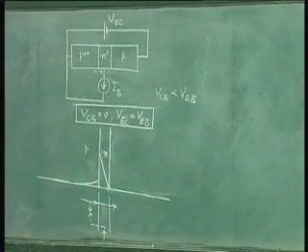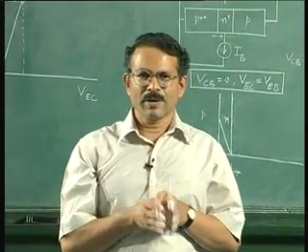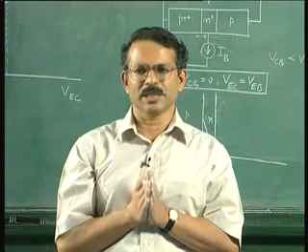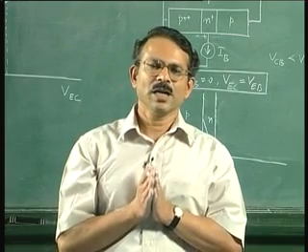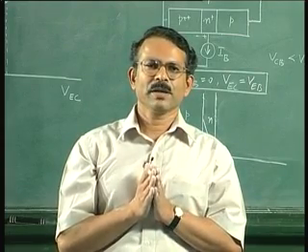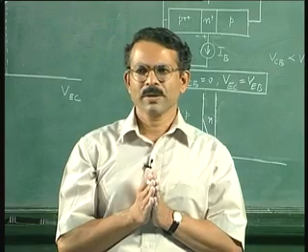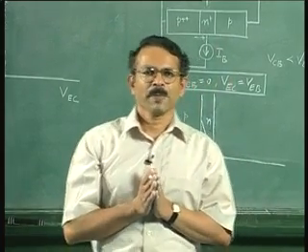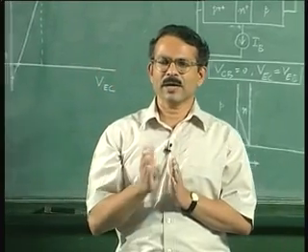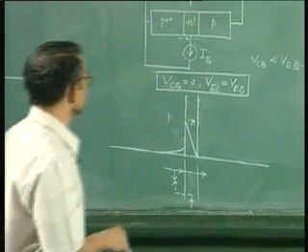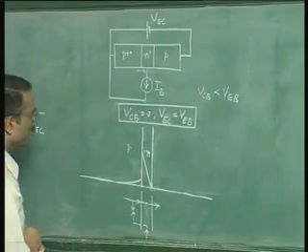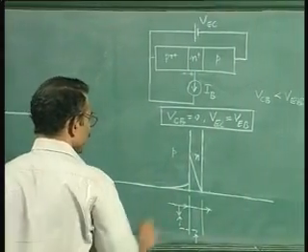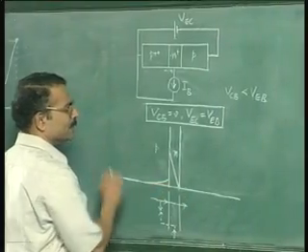This we have discussed in our earlier lecture, that what is the effect of having a reverse bias across the collector base junction, and we said there are two effects. One is there is a reverse leakage current ICO, and another is that there is base width modulation, okay, and this base width modulation has an effect on amplification. Now right now we are interested in the base width modulation effect on the IC VEC characteristics. So for that purpose we must now show the base width also clearly.